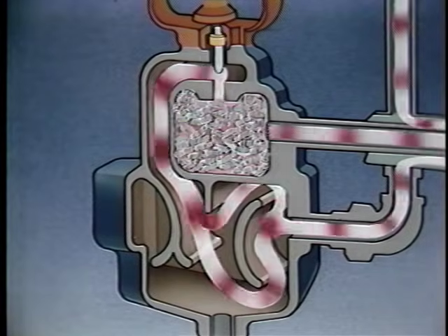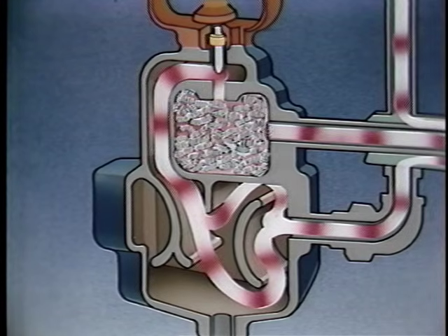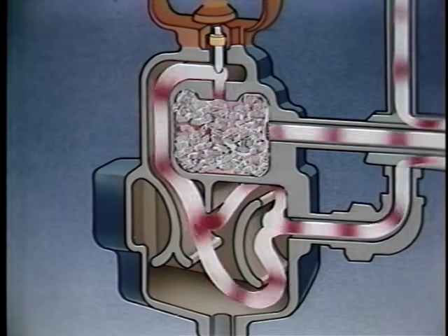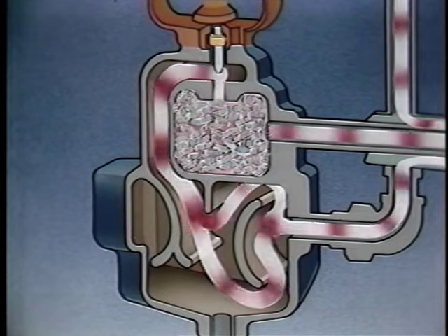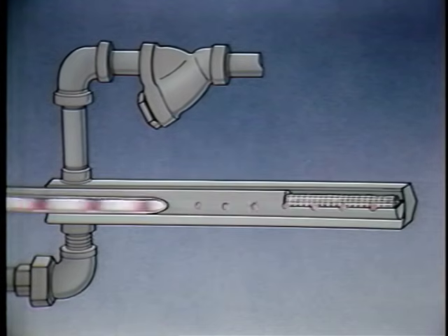The drying chamber is filled with a stainless steel drying material, which also serves as a silencer or muffler for the escaping steam. The short path from the humidifier to the jacketed distribution manifold, like so many other features of the Series 9000, was chosen to minimize radiation losses and condensation.